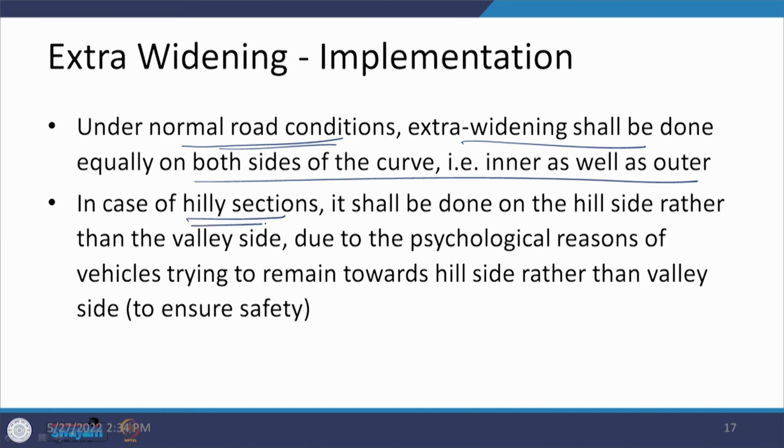In the case of hilly sections, what we are going to do is that it shall be done on the hillside rather than on the valley side, due to the psychological reason of the vehicles trying to remain towards the hillside rather than the valley side. And the reason is clear.